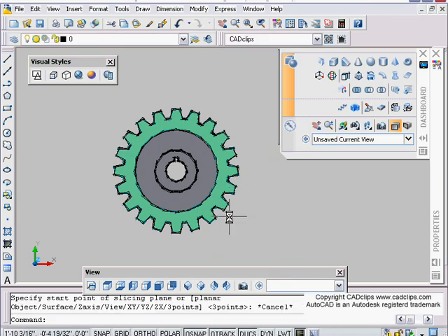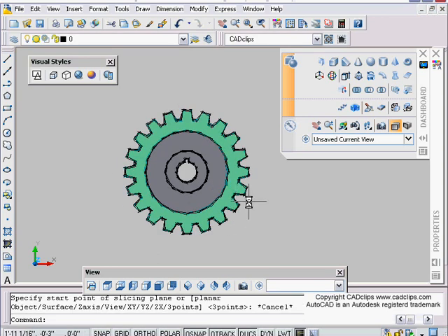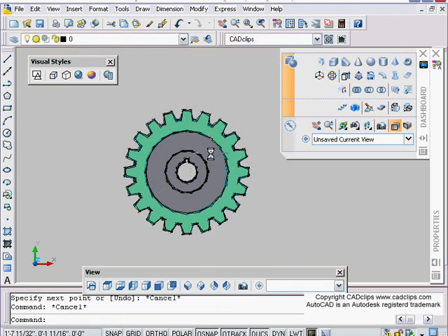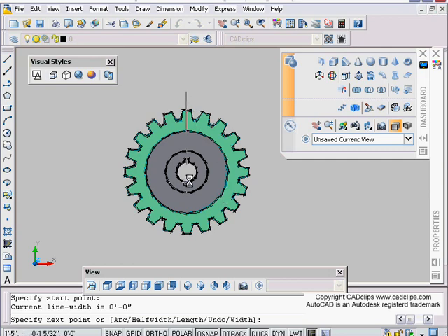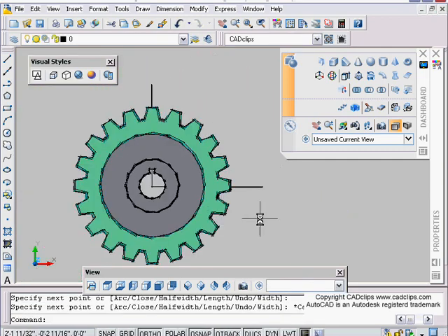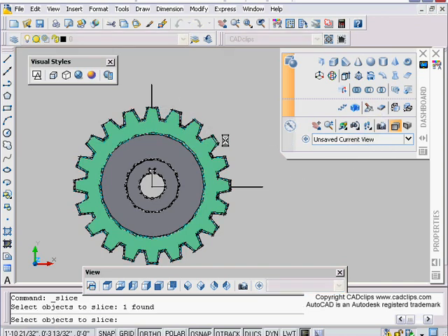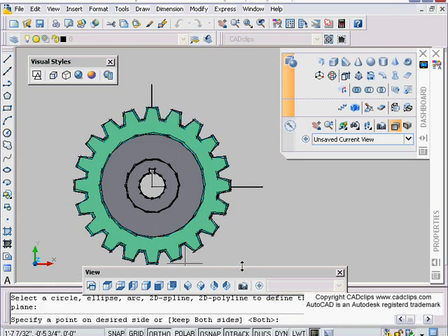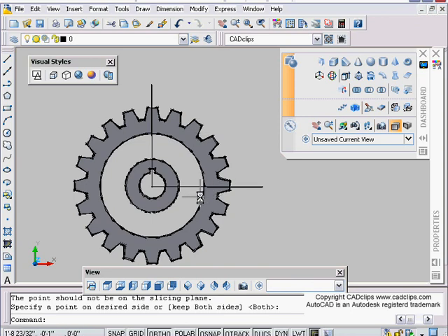The interesting thing is a lot of times what I did initially was to, for instance, draw a line that might go from here, or a polyline, because you can use an object to slice. I thought I could draw an L like that and then go slice, pick this, enter, use the O for object and pick this, and then try to select a side, and it won't work.